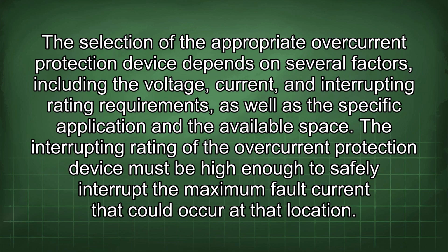The selection of the appropriate overcurrent protection device depends on several factors, including the voltage, current, and interrupting rating requirements, as well as the specific application and the available space. The interrupting rating of the overcurrent protection device must be high enough to safely interrupt the maximum fault current that could occur at that location.